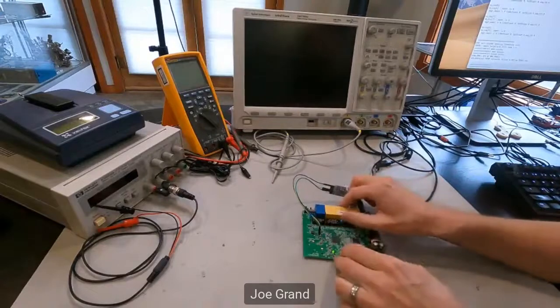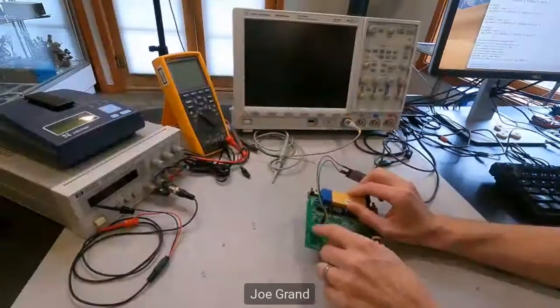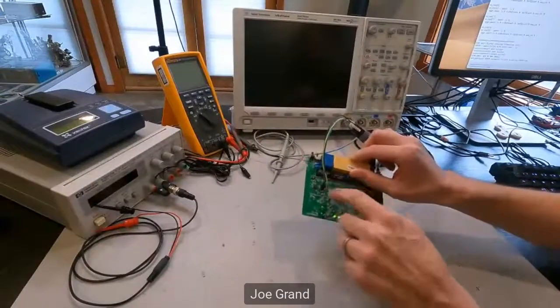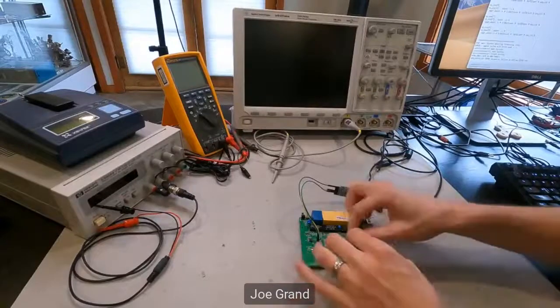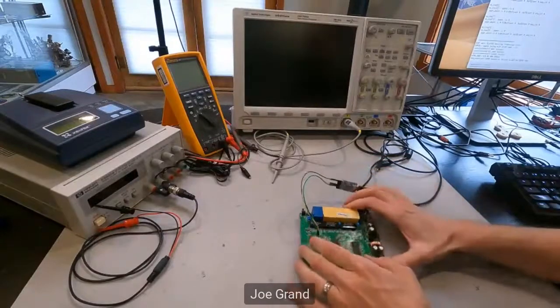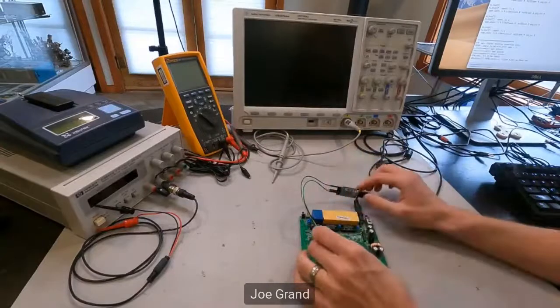Maybe you'll see test points instead, which are just copper pads on the board. You might even see some silkscreen markings. So on the board, there's white lettering. Sometimes it's going to be other colors. And engineers put that on there to help them identify what parts are what on the board to make it easier for testing and debugging. So it might even say UART interface or transmit or receive.